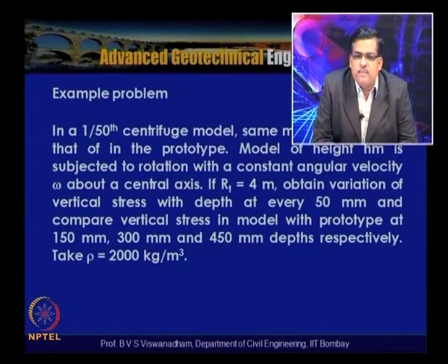So by knowing omega, and by writing the depths and the stresses in model and prototype at different depths, we can find out the variation of vertical stress in the model as well as in the prototype. If you look into it, at a depth exactly at 2 Hm by 3, that is 2 into 450 divided by 3, around 300 mm, you will see that the stresses in model and